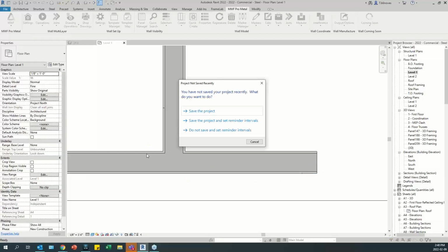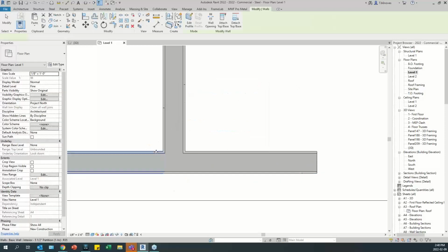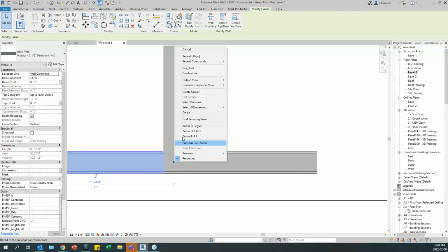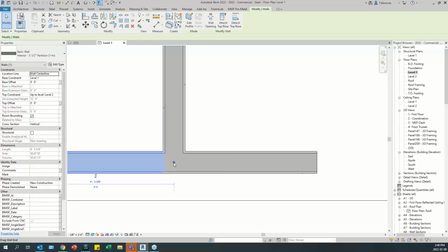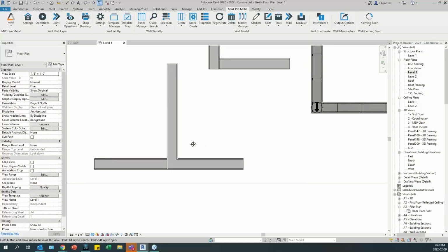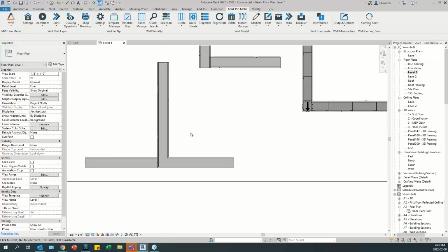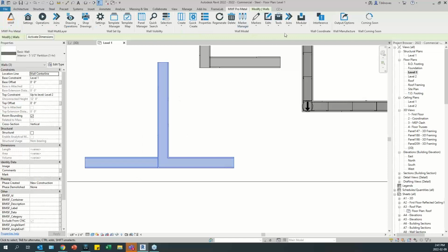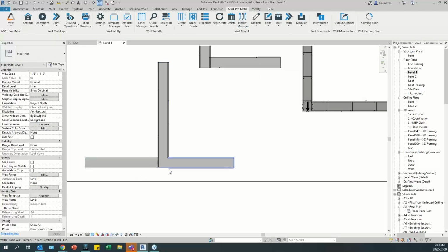Okay, so you do have this, but one of them is not joined, right? Yes. So I pull that, do disallow join, and I pull it back to the face of the other wall. Oh, okay. So I'll run auto, so I have like a two wall auto join rule set up, but it'll give me an error at this condition because it's viewing it as three walls. I see. It shouldn't be doing that.